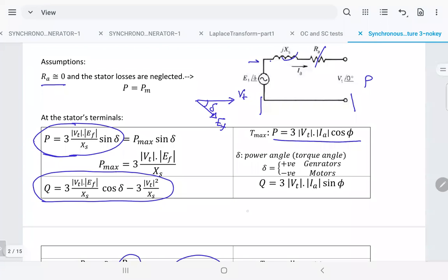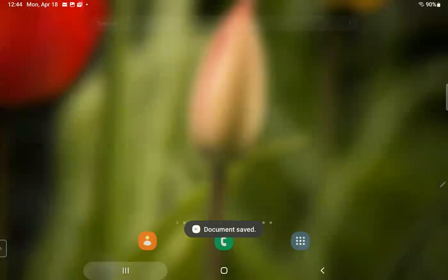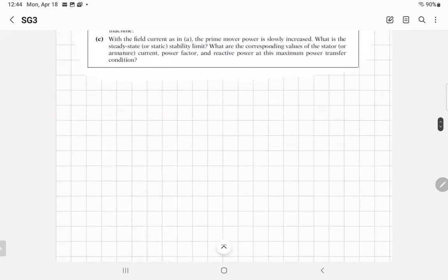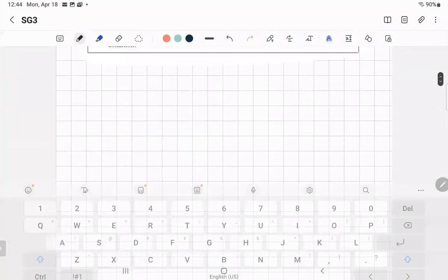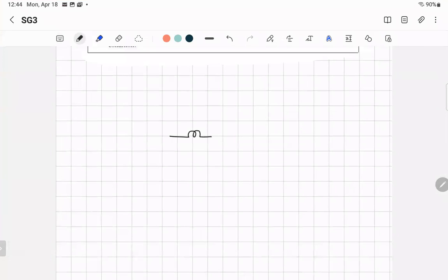If you have any system like that, you can represent it as a voltage source, and you have a bus bar or infinite bus and a transmission line, always represented by X, as I said, JX. If you want to include also the synchronous reactance of the generator, and then you have the reactance of the transmission line, call it T, and then you got the terminal voltage. In this case, you make the equivalent circuit. Let me show you how you do it. You are going to make it like that. You will say that's the generator. That's how you represent the generator.